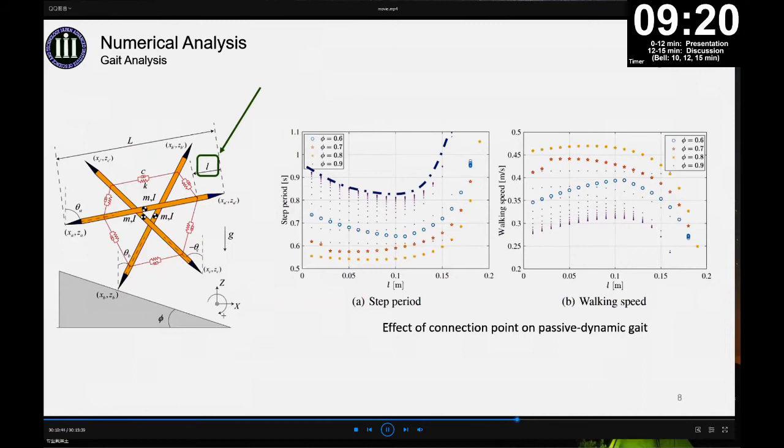This indicates that the potential energy of each step cannot be completely consumed by collision, because by the elastic elements, part of the energy is converted into elastic potential energy inside the robot. Consequently, the rest of the energy remains for the next step, so that the chaotic gait has appeared.